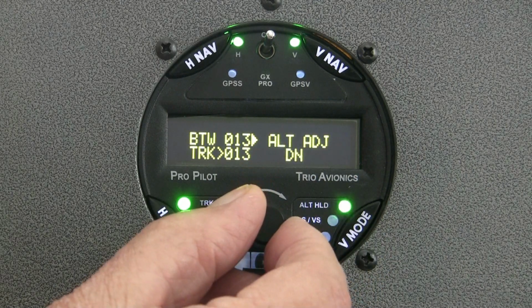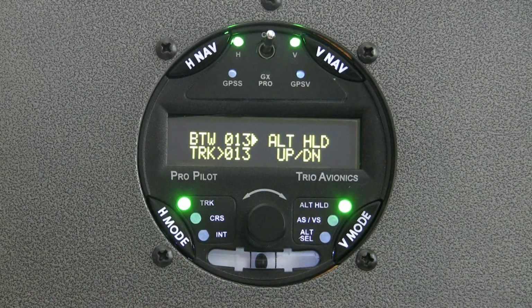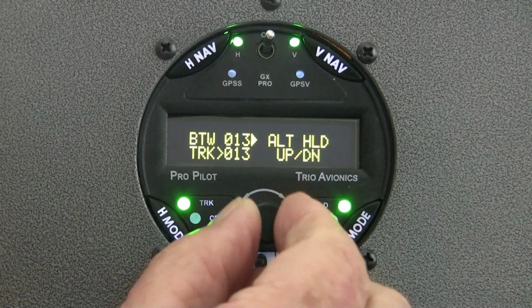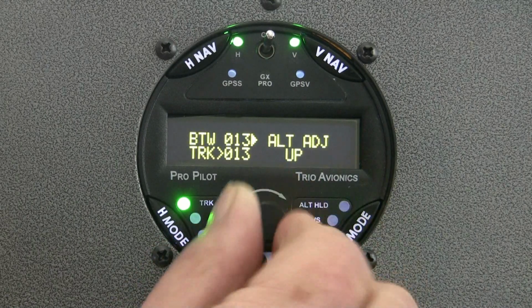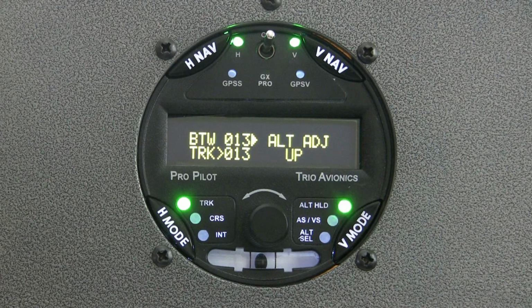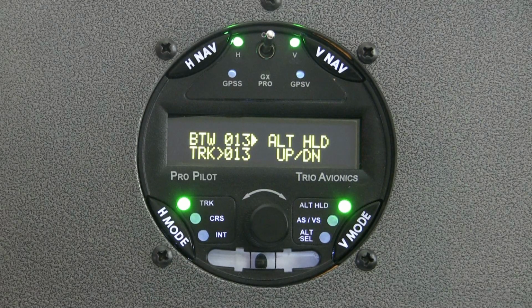This function is useful when you get a new barometer setting for your primary aircraft altimeter after flying for a while. When the primary aircraft altimeter is then adjusted, it may show that the aircraft needs to climb or descend a bit to re-establish the proper altitude. If the altitude error is more than a 20 or 30 foot error, the encoder can be rotated a few turns and the aircraft will then climb or descend slowly at about 100 feet per minute. When you have reached the corrected altitude, simply press the encoder knob and the autopilot will again be in altitude hold.